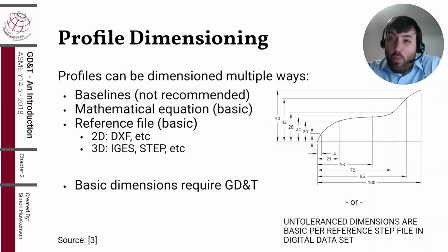Okay, so what does ASME Y14.5 say about dimensioning profiles? Now, this is something that I personally was puzzled about before learning about Y14.5: how you're really supposed to dimension, let's say, organic geometry or some complex shapes on a drawing. And I believe the oldest way to do it is what you see on the drawing here. It's with baselines.